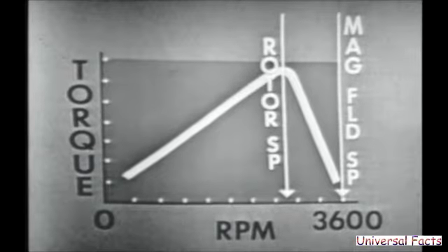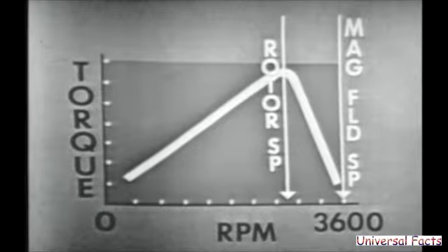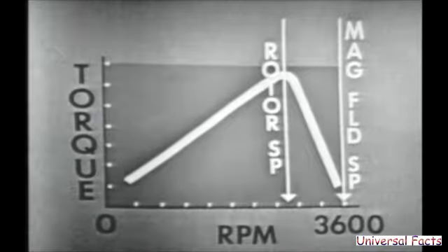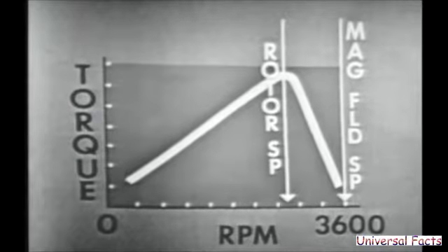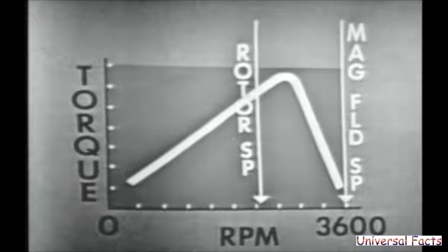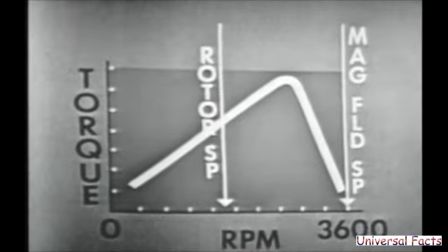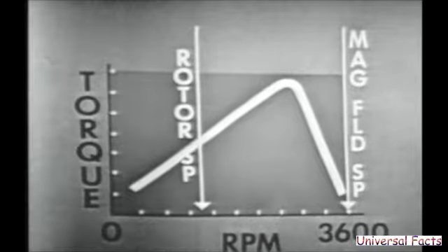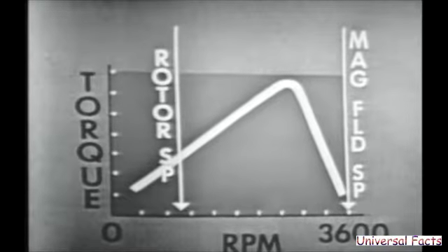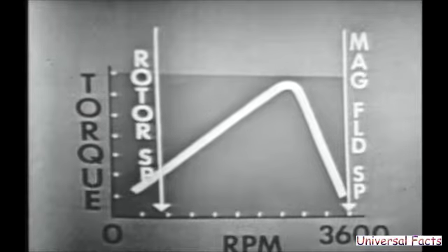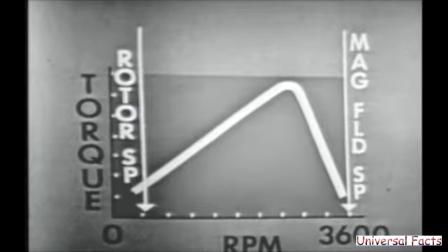But at this point now, torque is maximum. Now, if the load is increased any more, as when Bob held it with his fingers, the rotor, of course, must slow down. The frequency of cutting goes way up to the point where the inductive reactance becomes large enough now to start limiting the current flow in the rotor. The strength of the electromagnet decreases, torque decreases.